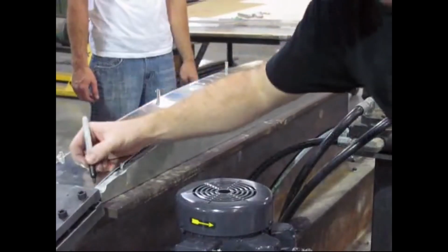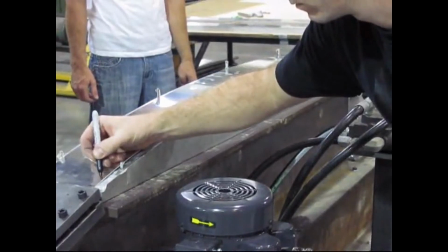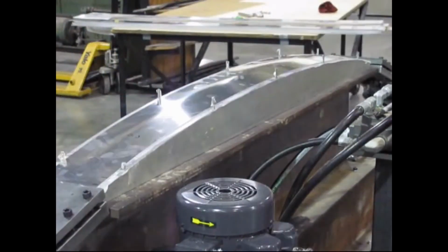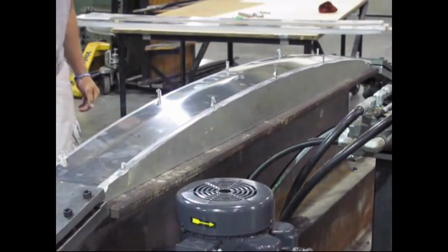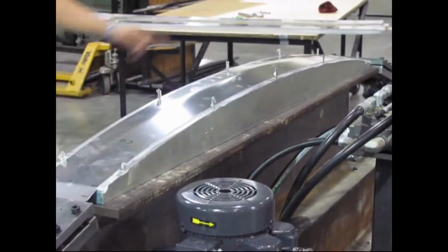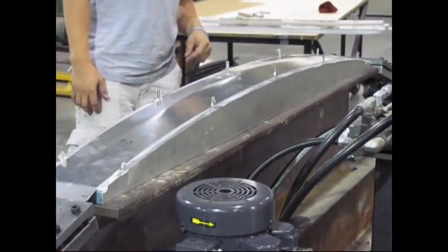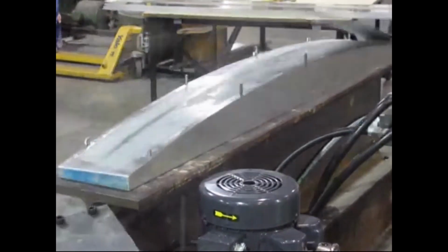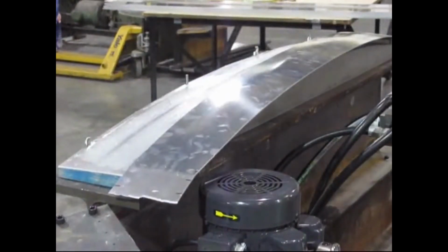The first method is stretch forming. First, on a bent die with a curved surface, the panel is stretched to form a primary curved surface. First, mark it with a pen. Then pull the metal to the marked point.